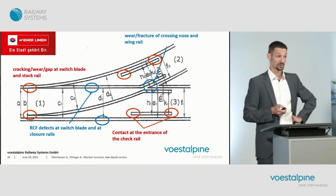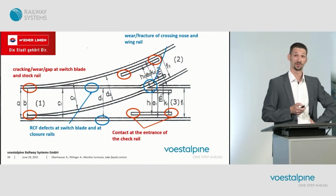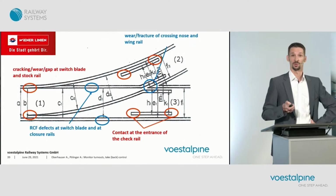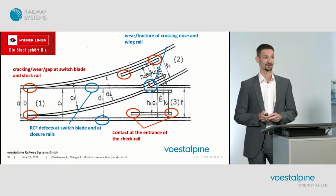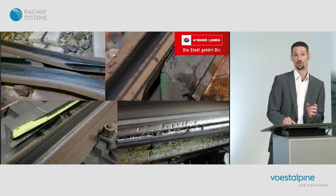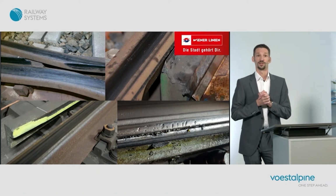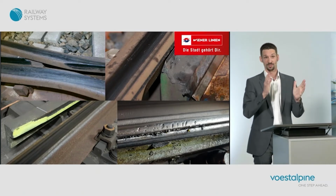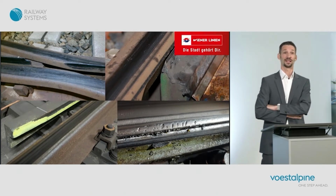And the fourth defect, also very important, is wear or rail fractures of the crossing nose and the wing rail itself. In order to give you some images how this looks like, I brought you some photographs from our track. On the top left, you can find a fracture of the crossing nose on the left.